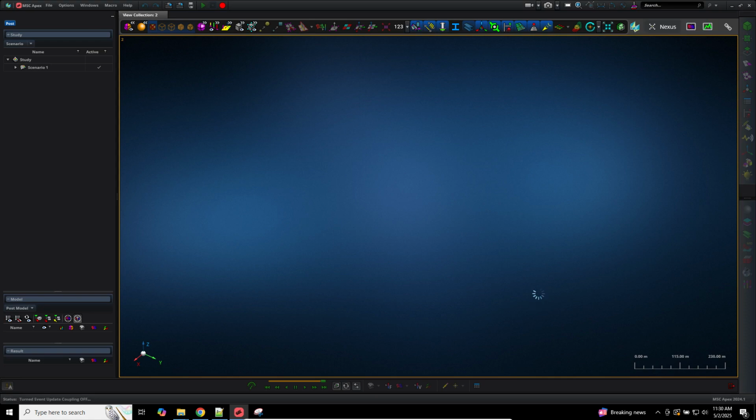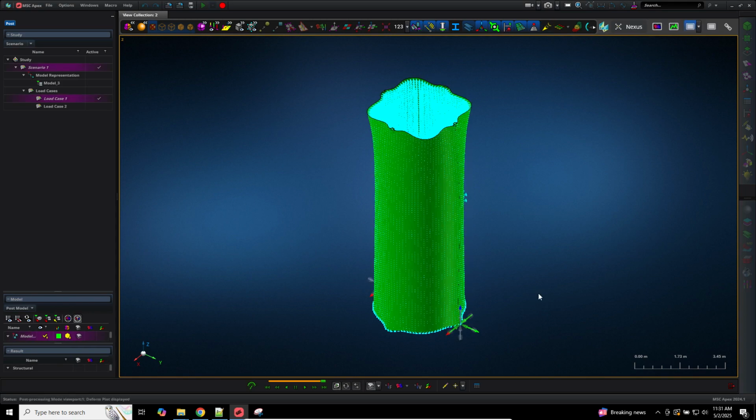Now we want to confirm one thing. Do we get radial expansion? Now, this worked if you only consider the cylinder. This may not work if you include other things like the stiffeners. If your composite material is asymmetric, this won't give you radial expansion.